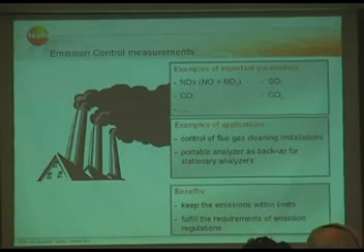And that means with the CTM, the test methods in the US, if you measure according to this test method, you can use any analyzer as long as you can show the quality of the readings, like stability tests and calibration tests. Everything can be fulfilled with the analyzer. You can perform those measurements with electrochemical sensors, for example. Just to make sure that the reading is okay and that there is no drift during the measurement, they require a pre- and post-calibration before each measurement.